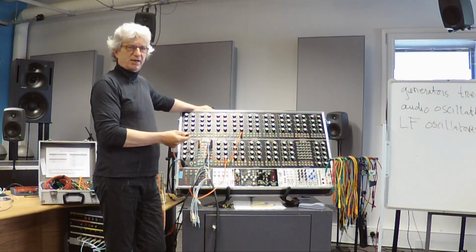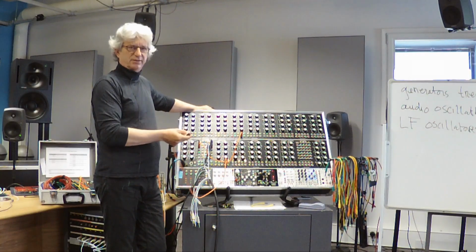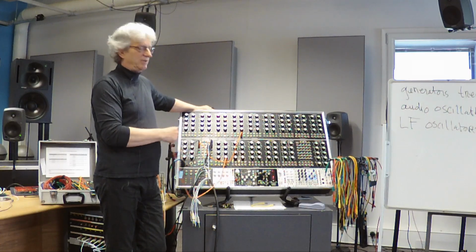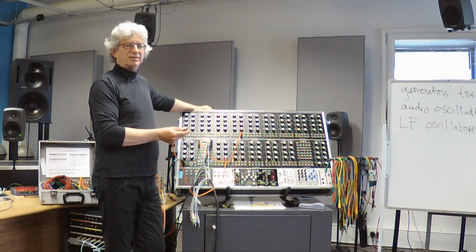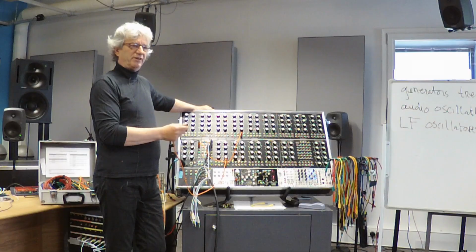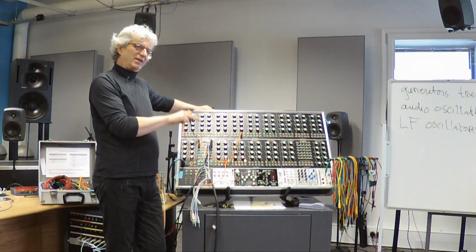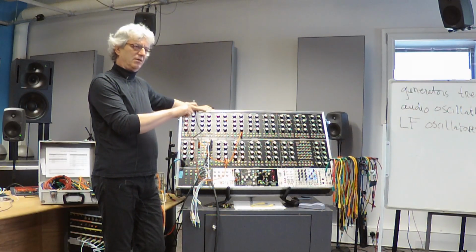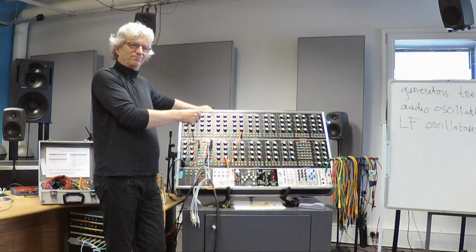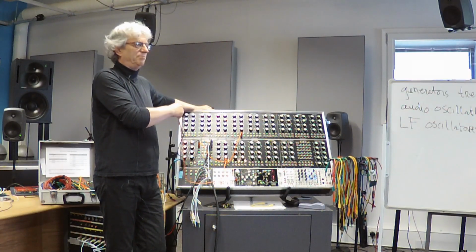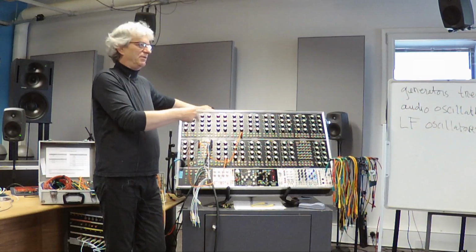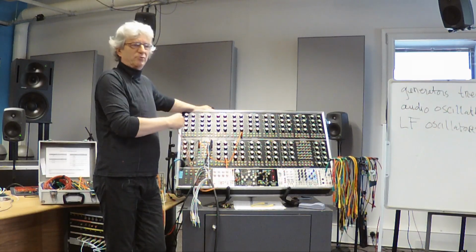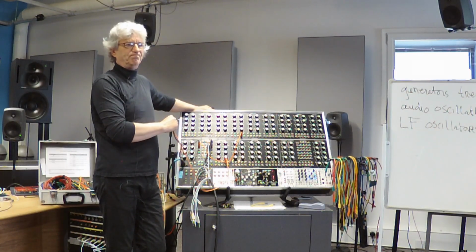And wave shaping basically is a means to add harmonics to a sound. But all wave shaping methods in general are very sensitive to the sound level that comes in. So if you would have an oscillator where you cannot control its output level and put it into a wave shaper, then this wave shaper will immediately go to max.